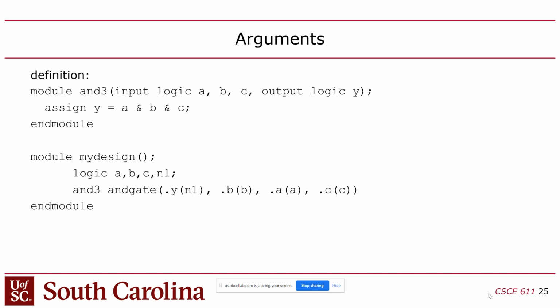So the problem is that if you go in and try to debug this on the FPGA, you use something called JTAG, and you can actually go inside of it and do a boundary scan and find signals in the hardware. The problem is that you don't know what it's called after it gets flattened, right? That same wire has two different names here, but remember, when you synthesize, it flattens it. It takes all this hierarchy out, and then it just gives it one name or the other, right? So then it becomes hard to figure out what that signal is in the actual hardware. So that's another reason why it's better to debug in simulation than to try to do it on the FPGA.